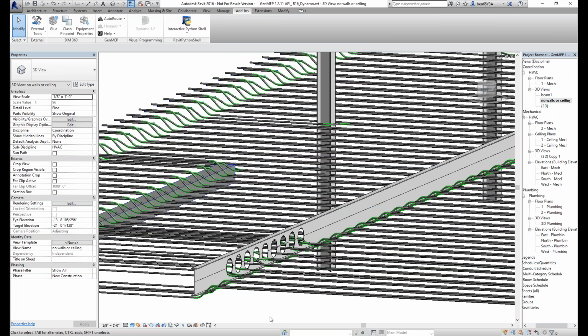The next question was, and I think this was particular to electrical, are the components industry standard, or is this a field bend install? And the answer is that we use standard Revit families for everything that we do, so the fittings are actual Revit 45s and Revit 30s and Revit conduit. So they're not field bent installations. They're actually a definable part.